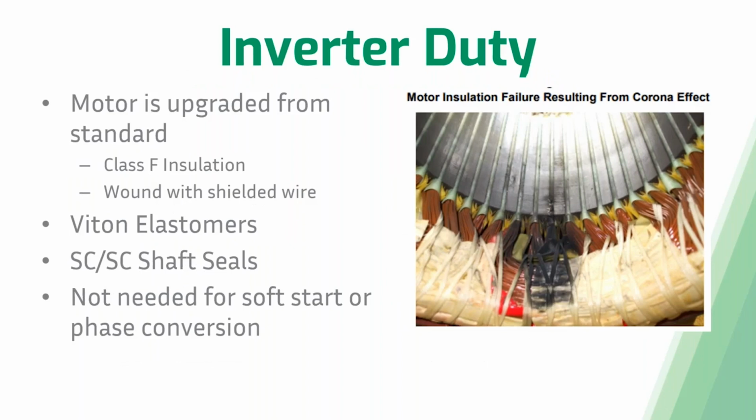Typically, if you're going to be using a VFD, you're going to want an inverter duty rated motor. This just means that it is an upgraded motor from the standard motor that pump would come with. It comes with a Class F insulation for that wire, and it's also wound with shielded wire as well. The reason for that is VFDs can start to create hotspots on standard motors, which can cause a premature failure inside of that pump, which you can see here on the right.